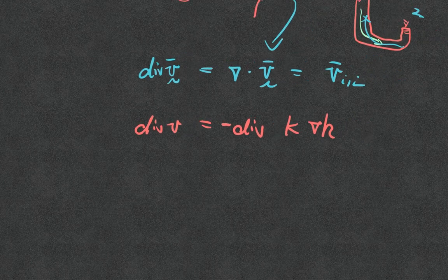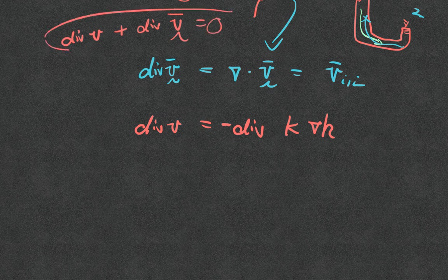So what should I do to further make it a one unknown problem so that I can solve it? Our equation is the divergence of the solid velocity plus the divergence of the Darcy's velocity equals 0. Now what if the material is rigid? What if the solid phase never deforms? If it doesn't deform, the velocity is 0, right? This is how in undergrad we draw the flow net. What the flow net is solving is these equations, this equation in particular.